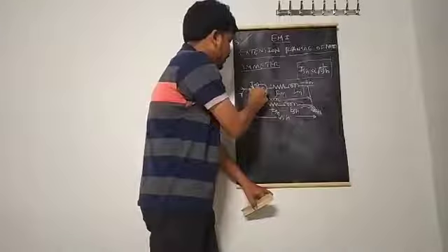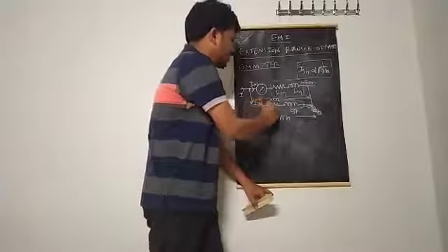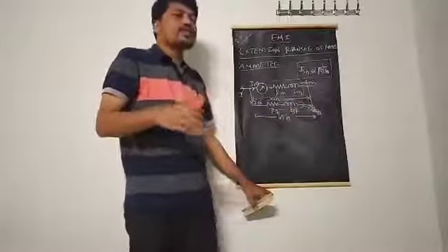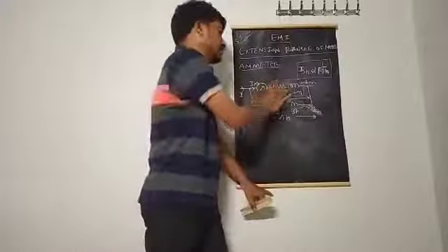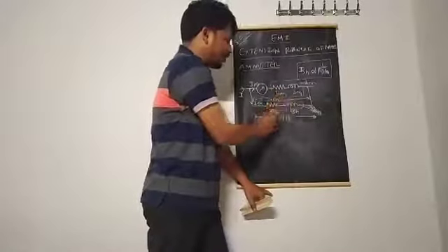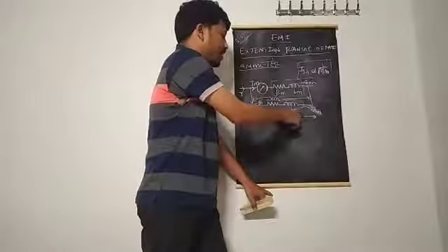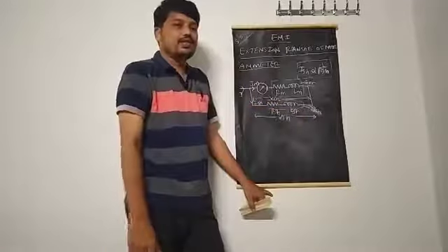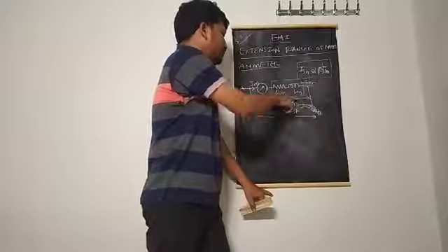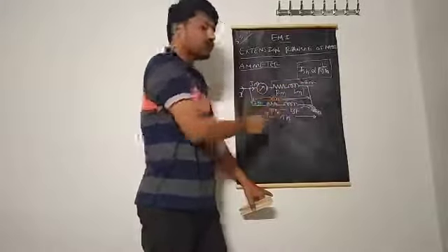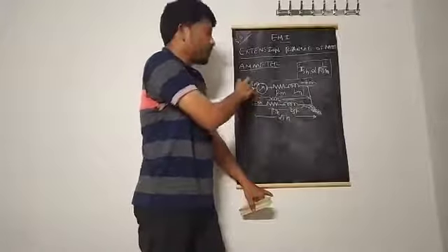Here this is the meter current, this is the measured current, and this is the shunt current, this is RSH. That means if you want to extend the moving iron meter as an ammeter, we connect a shunt resistance across the existing meter resistance and meter inductance. We take RSH as the shunt resistance and LSH as the shunt inductance. The voltage across RSH and LSH is VSH, and the voltage across the entire meter is VM. The current flowing through RSH and LSH is ISH, the current flowing through the meter is IM, and the current to be measured is I.